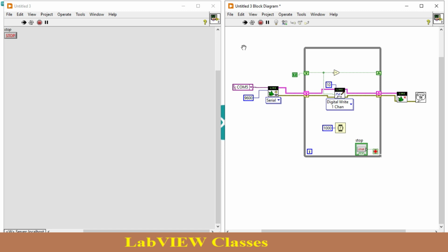And if you want to change the duration also, you just go with the PWM pin. Right now over here it is not possible to change the duration of this high and low, because in this case the high low duration is fixed. Right now it is 1 second; you can make it 2 second, 3 second, 4 second, it is up to you. But you cannot change the duration like 2 second on, 4 second off. For that purpose you go to the case structure, and over here you put your timings. Is it clear to you?